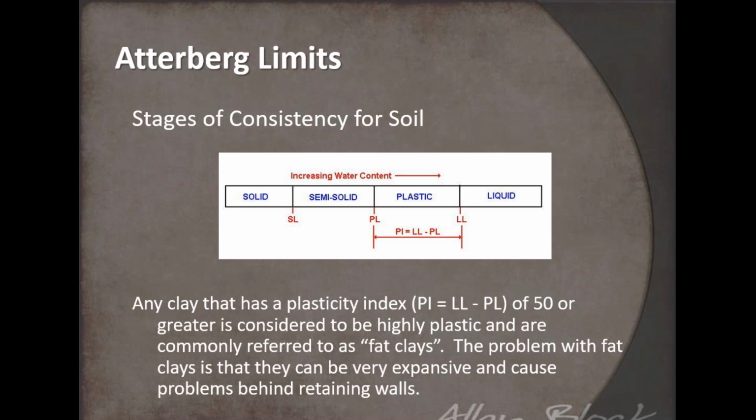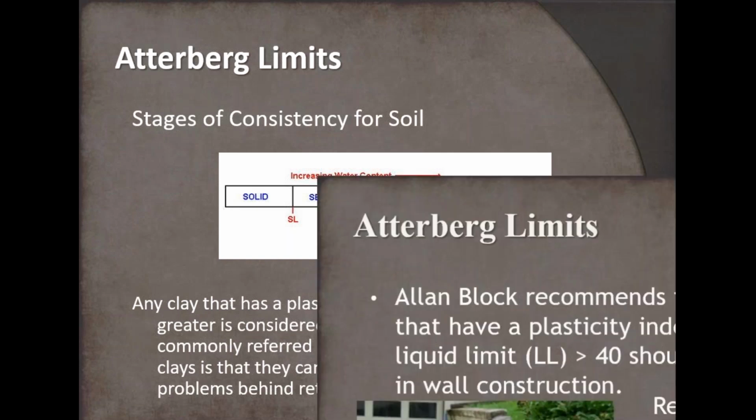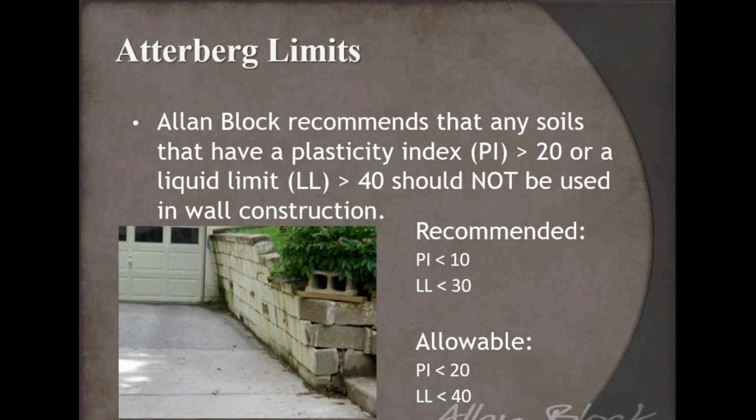In our industry, we start looking at plasticity indexes greater than 50. That means you're dealing with a very fat or heavy clay. All that means is you've got a clay material that is going to be very, very expansive. It's got those properties that when water is introduced, it's going to expand and cause problems behind that retaining wall. And we see it all the time. Anytime you're building in expansive clays, it may look okay, but then as water is introduced, it'll start creating that additional pressure. Not so much hydrostatic pressure per se, but soil pressure, because it expands.